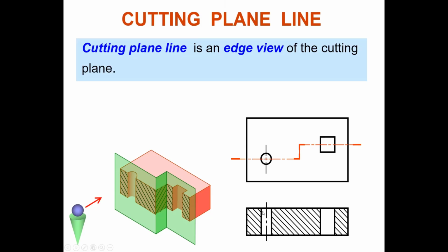If you look here, the round hole has a center axis. Why doesn't the square hole have a center axis? Please take note of that. Because round holes have a center line, a center axis, but the square does not. Clear? If you make a center line on the square hole on your front view, people will misjudge. When they quickly look at the front view, they will think the right hole is also a round hole. So be careful about that. The square holes have no center line.